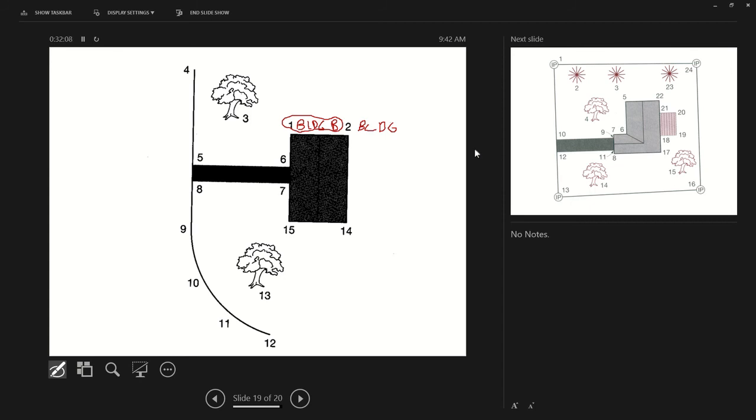All right, so then we go to number three, and it looks like a tree. They go and collect it here, and it's a deciduous tree, so it's DTRE. There's no space B or anything there because it's a point code. It's identifying just a single tree, so there's no reason to start a line there, and you don't want to put a B after that. So it's just DTRE.